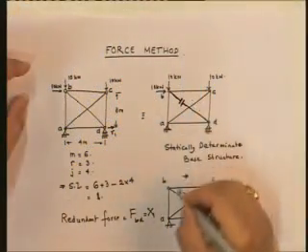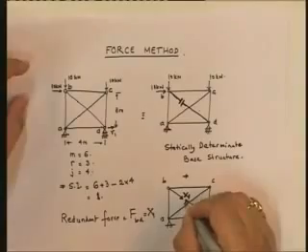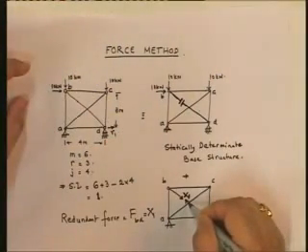Now how do I do this? This is a displacement. I need to find out a displacement. How do I find out a displacement using the method of virtual work? Use the method of virtual forces. What does it mean? Since I'm trying to find out the displacement at this point relative to each other, I apply a virtual force at this point and compute the work done. The total work done has to be equal to 0. That gives me the displacement. Now, what is that force? Note that the force is exactly the same as the redundant force.